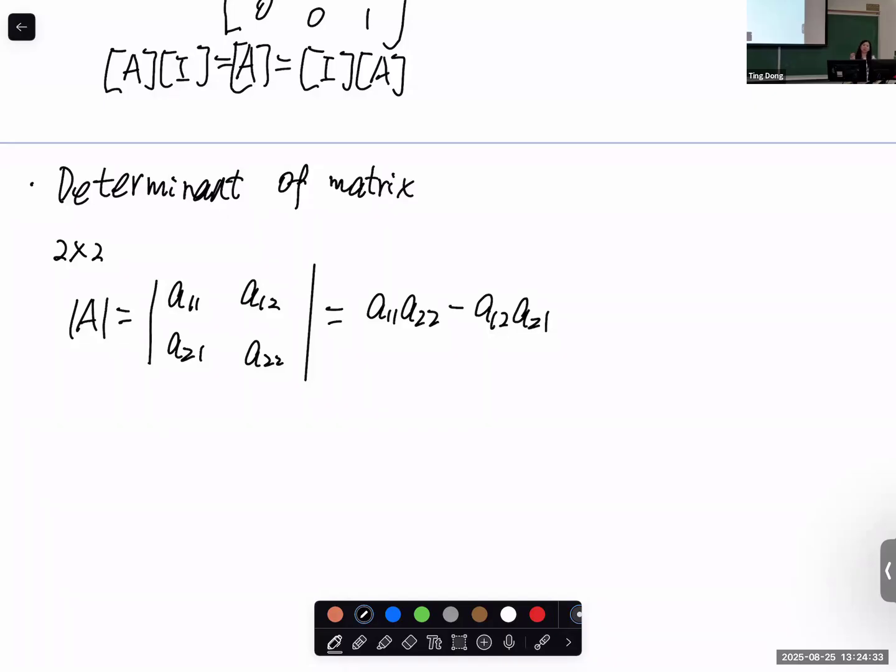transition step when we need to calculate the inverse matrix, because, let's go back to FEA. We have the K matrix, the stiffness matrix for the structure. We have the degrees of freedom you need to solve. We have the force applied vector, K times Q equals F. So what do we need to do in FEA? We need to solve for the Q vector. So it's the inverse of K times the force vector.